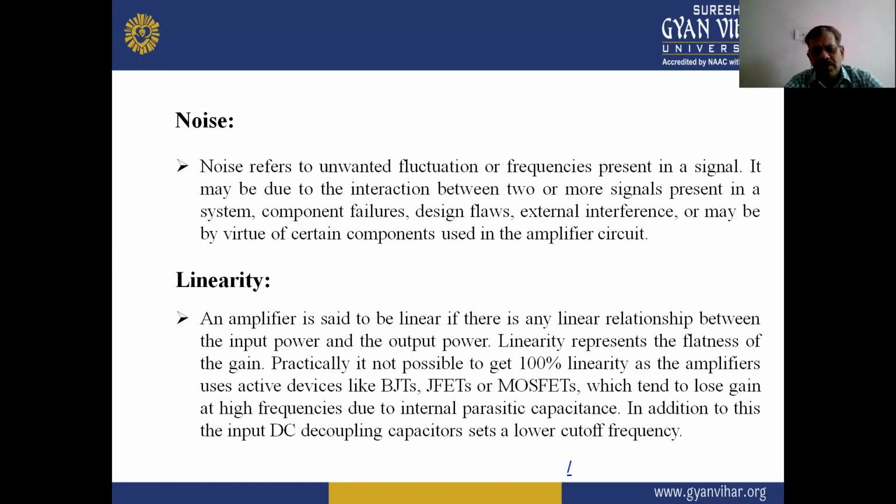Practically it is not possible to get 100% linearity, as the amplifier uses active devices like BJT, JFET and MOSFET, which tend to lose gain at high frequency due to internal parasitic characteristics. In addition, the input DC decoupling capacitor acts as a lower cutoff frequency.